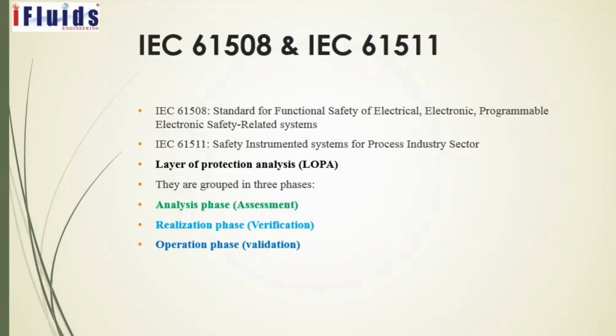So these are the standard codes which are used for SIL assessment. IEC 61508 is a common one, and IEC 61511. What are they? IEC 61508 is the standard for functional safety of electrical, electronic, programmable electronic safety related systems. 61511 is for the safety instrumented systems for the process industry sector.